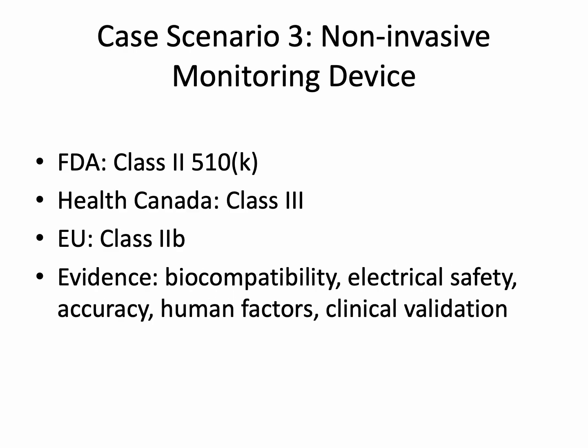Wearable continuous glucose monitors require a comprehensive testing approach. FDA Class II requires 510(k) submission, Health Canada Class III requires MDL with clinical evidence, EU Class IIB requires notified body assessment. Evidence includes biocompatibility of skin contacting components, electrical safety testing, accuracy and precision validation, comparison to reference methods, human factor studies, and clinical validation in the target population. This ensures device performance meets user needs and regulatory expectations across jurisdictions.